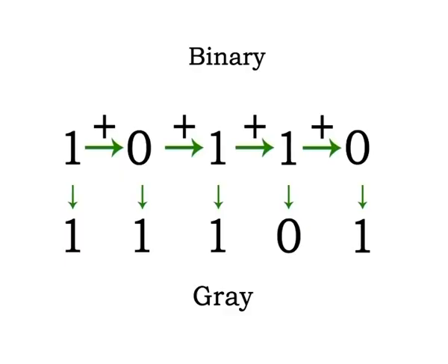The following rules explain how to convert from a binary number to a Gray code word. Begin with the MSB of the binary number. The MSB of the Gray code is the same as the corresponding MSB of the given binary number. Going from left to right, add each adjacent pair of binary code bits to get the next Gray code bit. Discard the carries.